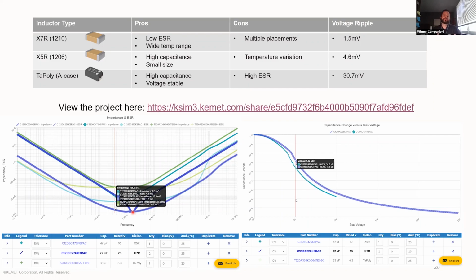But that current causes losses because of the losses in the dielectric itself, the ESR, and that's why the ESR is there. There's a component because of the losses in the dielectric, and a component because of the losses in the electrode structure itself, as well as losses in the termination material. So much like an inductor has different reasons for its losses, so does a capacitor. Okay. Yeah, it's one of those questions that seem at first easy to answer, and yet they're not so easy.